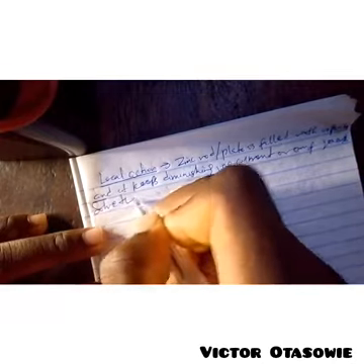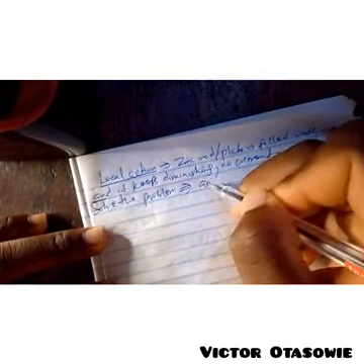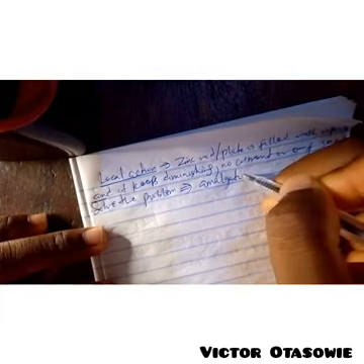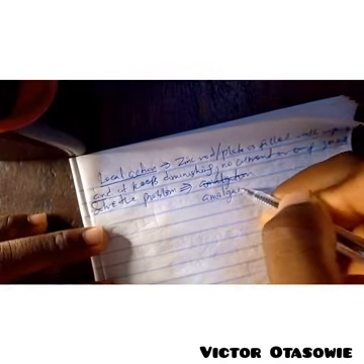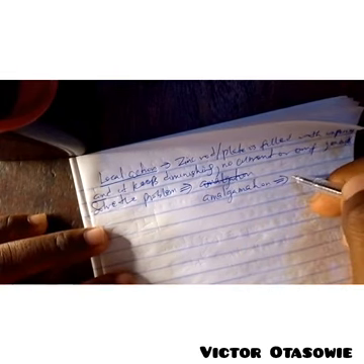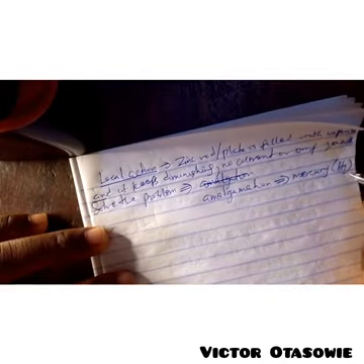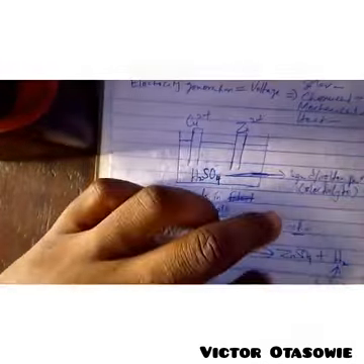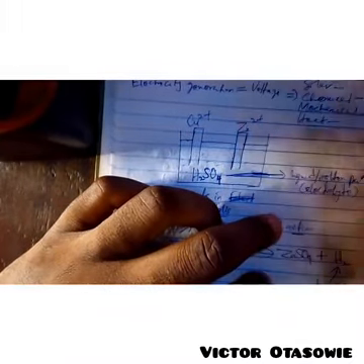So what occurs is, as a result of this, we now have to solve it. To solve the problem, we tend to use a process called amalgamation. And how do you amalgamate? You use mercury, Hg. Just come and say, oh, this is our zinc rod. Just come here and rub some pieces of mercury on the zinc rod.